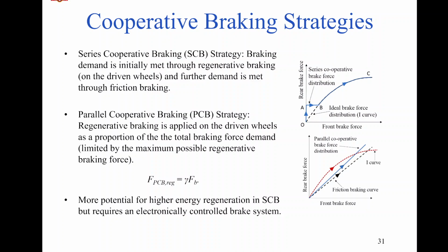Oh, okay. So the higher the level, the more aggressive the regeneration will be. It will almost stop the vehicle. If you go to level three, even without brake, it will try to stop at some distance. Okay, now I get it. That is the different levels of braking that is there in the Kona, and I think in the Mahindra XUV400 also they are putting it, allowing the driver to choose what level of regeneration he wants.